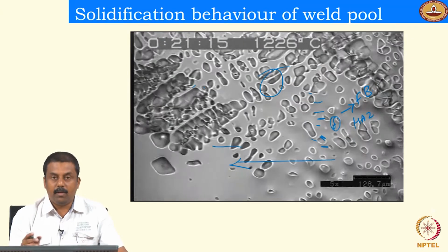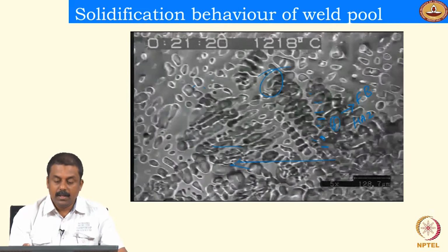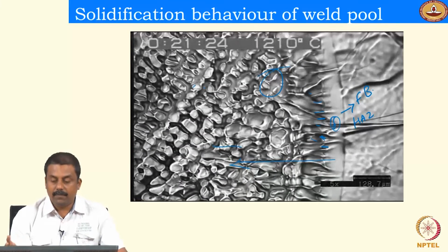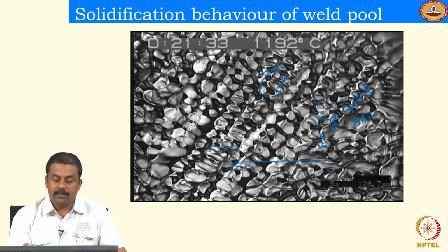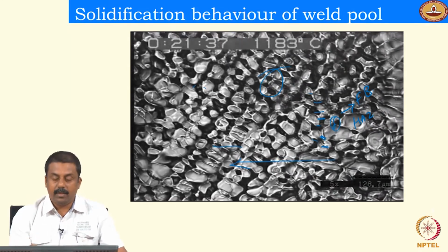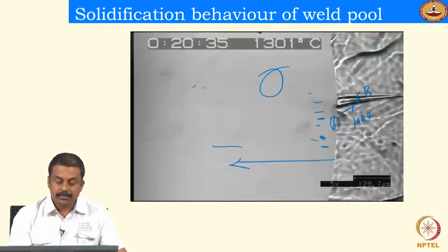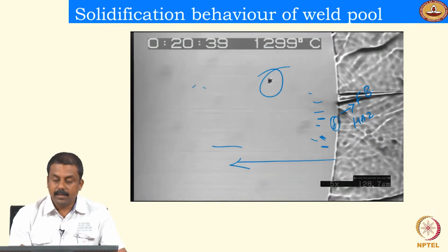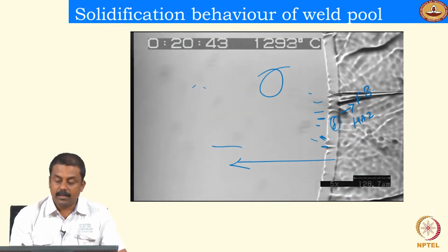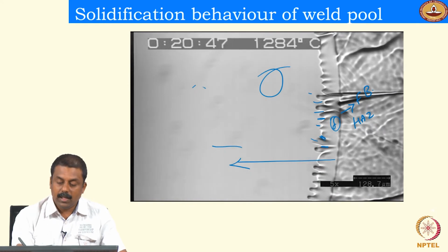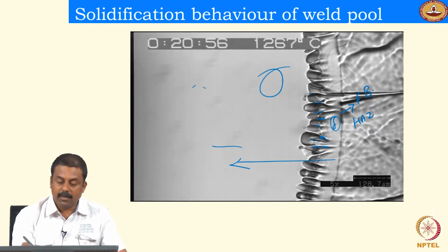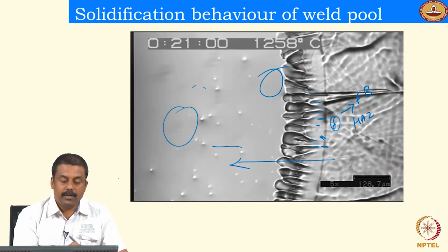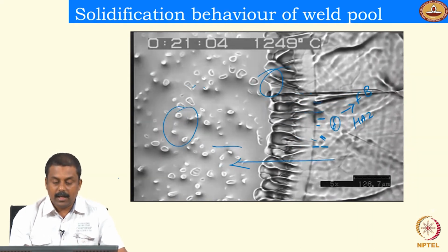Because the carbon concentration of the liquid is always higher than the solidifying product, the carbon would tend to segregate towards the unsolidified liquid, thereby enriching the liquid during solidification. So in this solidification mechanism, you will have a partitioning of carbon to the unsolidified regions at the interdendritic boundaries, as the liquid solidifies at last.